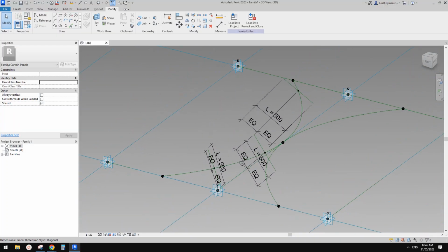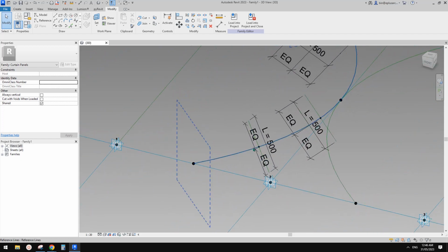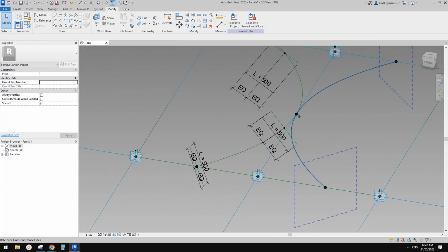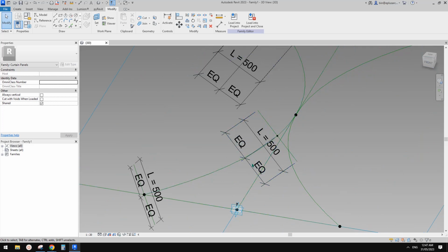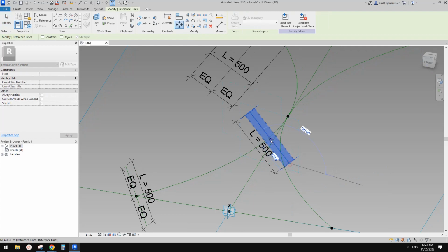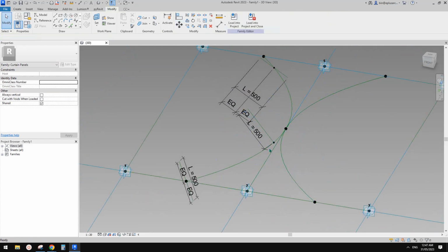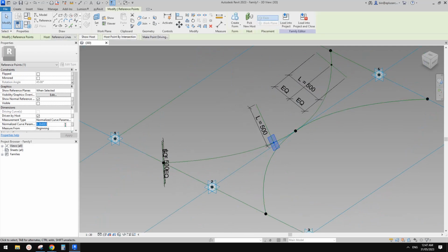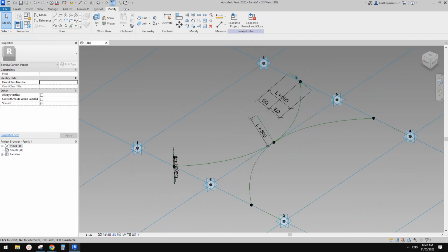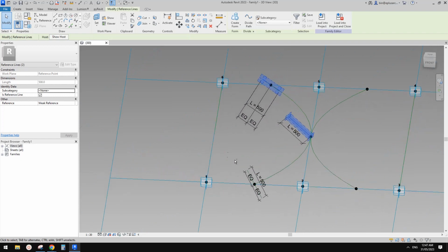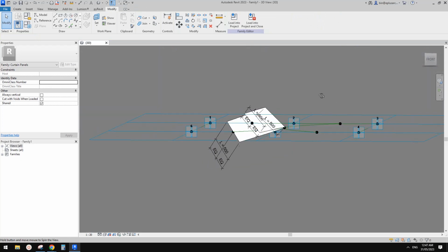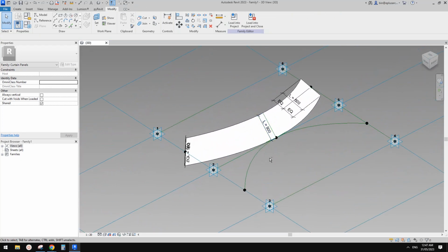Okay, so see here. At this point, we want this profile to be centered, you know, here, right? But at this point, we want this one. So actually, I need to remove this equal and then move this point to here. And then of course in the middle, I'll just type in 0.5. And then I'll just drag this to the end. Okay, so now we have 1, 2, and 3 reference lines. So we can create a form. So this is it.